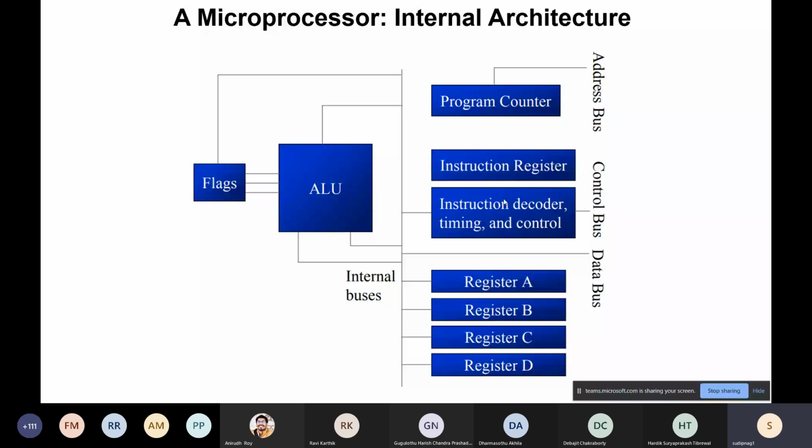So a huge decoder has been constructed inside. Assuming the data bus is 8-bit, like in AVR or 8051, that 8-bit data is sitting in the 8-bit instruction register, and all 8 bits are now decoded to 256 outputs. Out of all 256 outputs, only one output will be activated based on the value here, because considering all 8 bits together, there is only one single binary value.